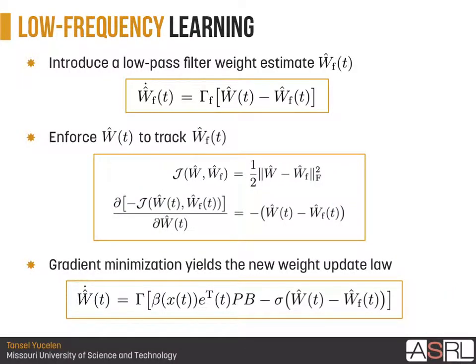So here is the idea. We have filtering tools like L1 adaptive control, but they assume a conservative upper bound on the uncertainty matrix W, and they designed very good robust adaptive controllers. However, here, I don't want to assume we know anything about the uncertainty. W can be anything, and we do not know an upper bound of W, simply because, let's say we know an upper bound, what happens if there is a failure to the aircraft airframe during the flight? This upper bound may change. So here I am not going to make that assumption.